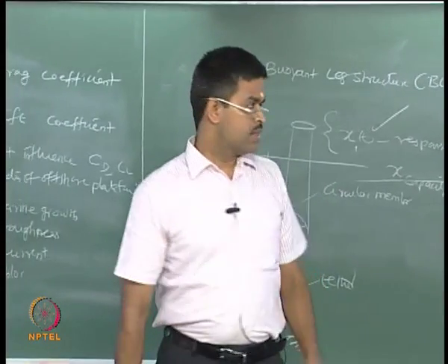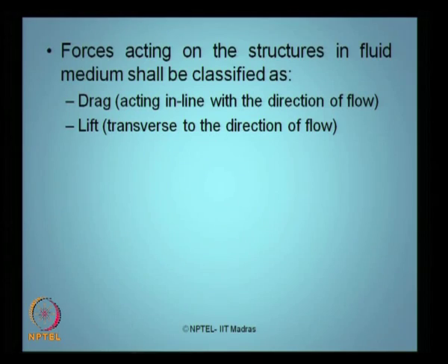So remember, drag and lift forces are essentially the restraints developed by the member to counteract the action of the wave or the horizontal forces on the member, essentially to keep the member in position.